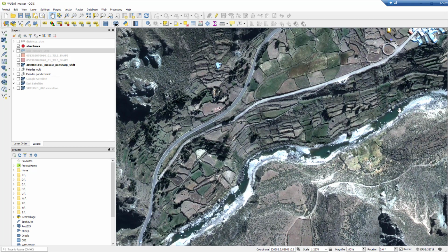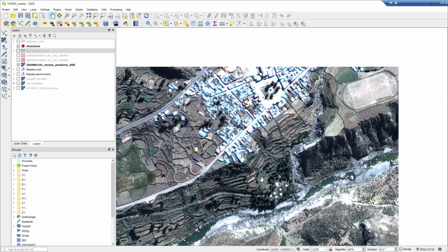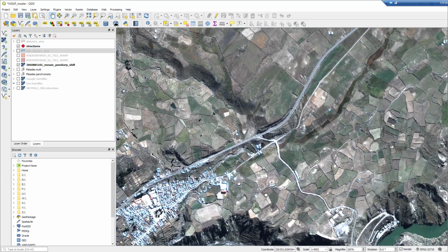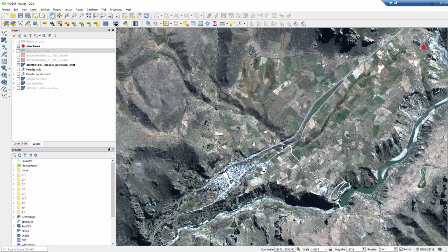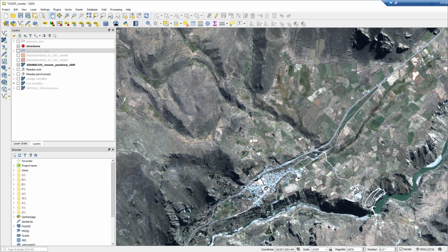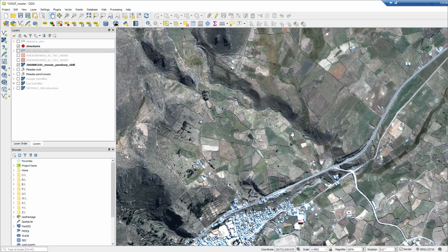This is a river right here, the Colca River. So this is the low spot, so we're going up slope. These terraces are all being actively maintained, obviously. And all these fields, technically, hydrologically speaking, are terraces also. They're just really broad terraces. So all these surfaces in the valley are optimized by people towards hydraulic management, towards irrigation management. They're all graded very slightly, to a 1 to 2 degree incline, or sometimes a little more, but they're optimized for the flow of water.